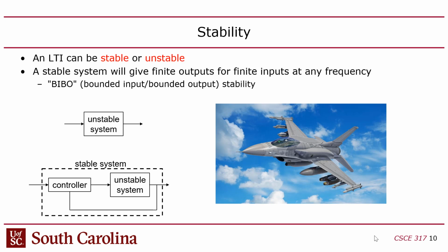And that's the nice thing about these S-domain transfer functions. If you model the plant, the thing you're trying to control, which in this example is the F-16 airframe and control surfaces, as an S-domain transfer function, and you model the controller as an S-domain transfer function, then you can create a new model of the controller feeding the plant in open loop control.